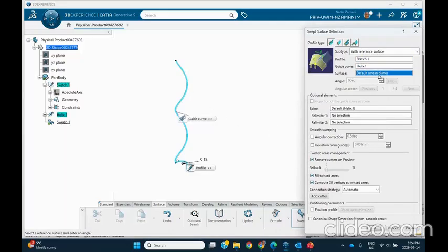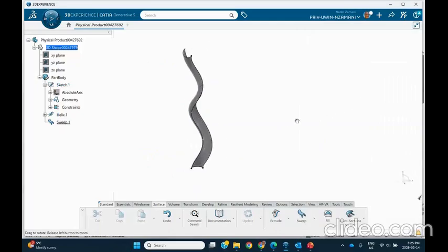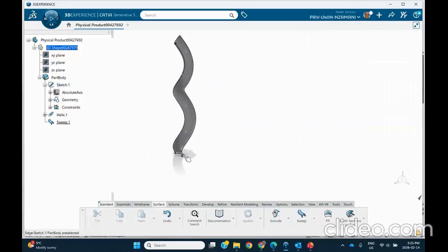And this is going to be the surface. Surface is the default, meaning surface. So I didn't do that. It comes because of my selection. And if you say preview, it looks like this, say okay. Let's see how it looks. So basically, it is this semicircle swept along that helix, and it looks like that.